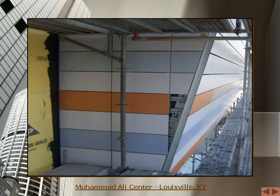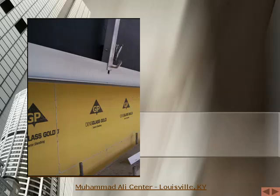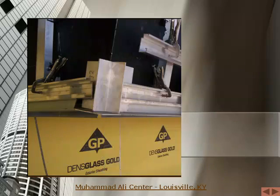With the ceramic tile rain screen system, tiles of irregular shapes, such as this corner area, can be manufactured to the required lengths and angles. A flashing system at the bottom of the rain screen wall is installed to route rainwater away from the building wall.